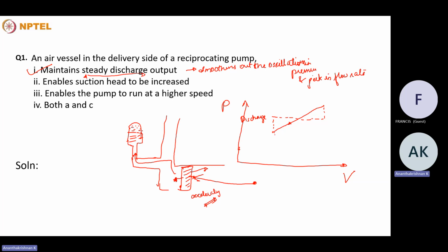So the pressure which is being delivered will not be a constant. When the pressure is higher than what we require for delivering the fluid to a required height, a portion of the fluid which is being delivered out of the pump will be going and compressing the air above the water column, and this extra energy will be stored as the change in energy of the air.